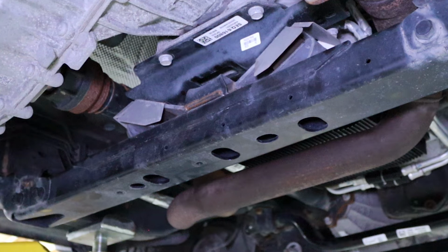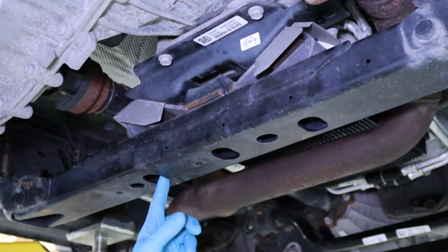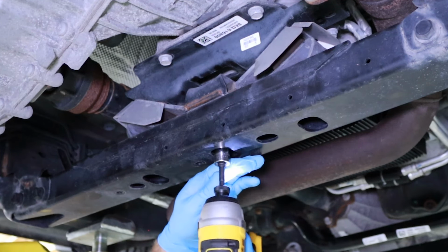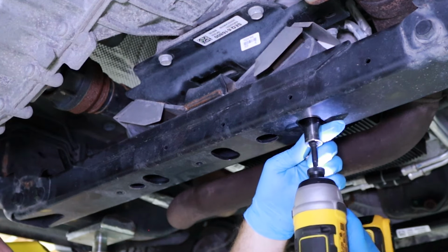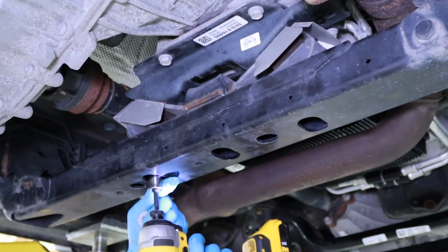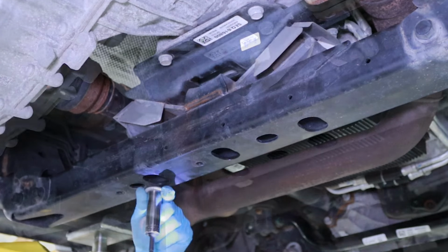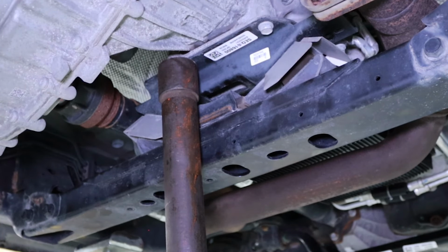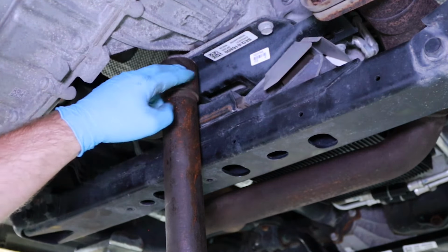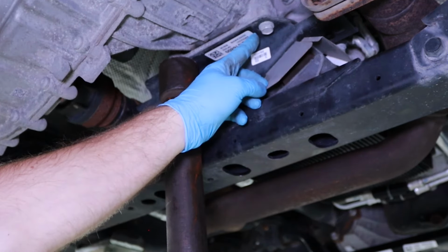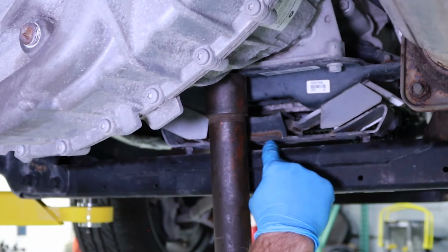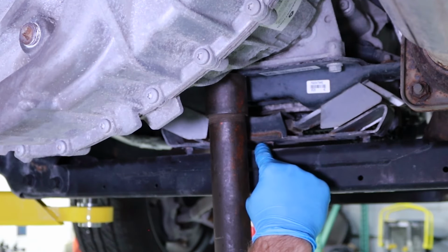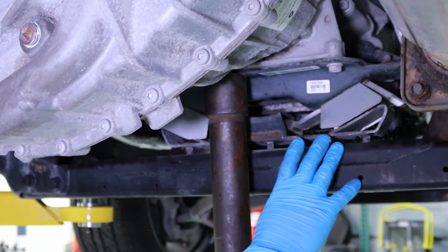In our case, we're going to be elevating the rear of the transmission by first loosening and removing the 3 transmission mount nuts located on the bottom side of the crossmember. Using a 16mm socket, loosen and remove the 3 nuts in a counterclockwise direction. Next, using a certified underhoist support stand, begin elevating the transmission by lifting on the steel area of the transmission mount support bracket. Lift until 1 inch of clearance is seen between the transmission mount and crossmember.